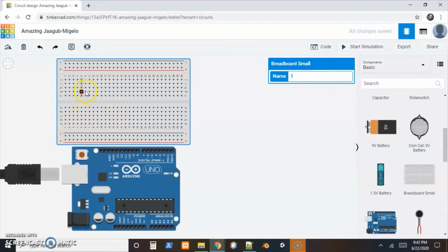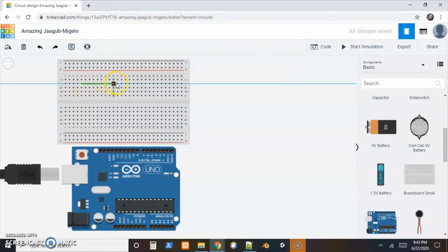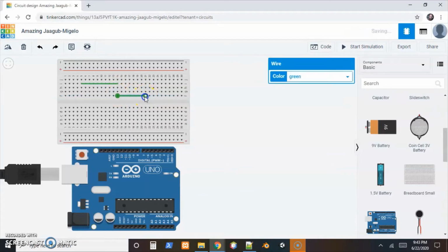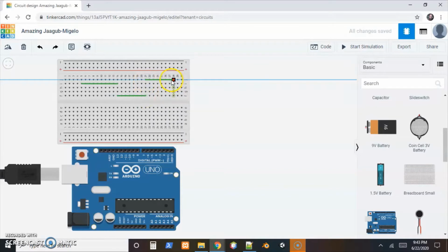And then these sections in the middle, these are where we form our connections. You can see from the highlighting there, all 5 of these pins are connected. So we'll plug the component into one spot and run it over somewhere else, and then come to a connected pin and run to another one, and we can form our connections that way.